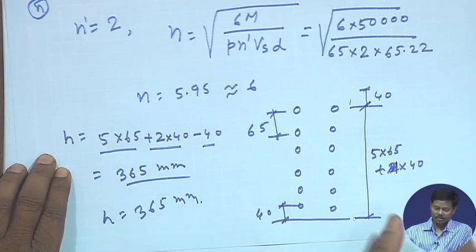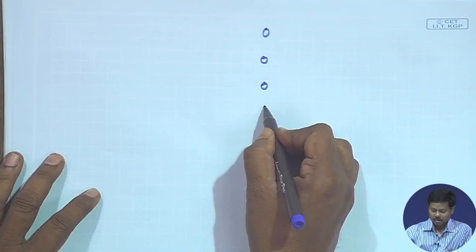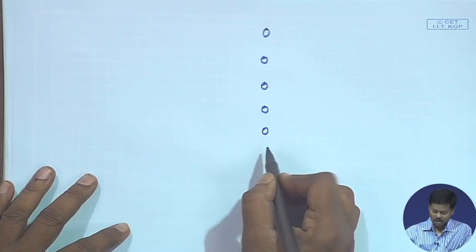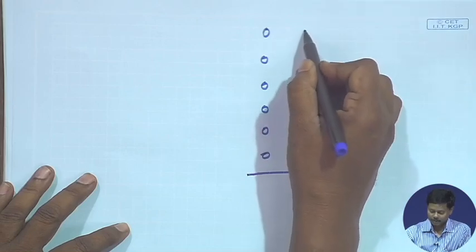Now I have to find out the value of TB, the tensile force carried by the extreme bolt, how much force is going to be carried by that extreme bolt. For calculation of that we have to know yi and summation of yi square. If we put those one by one, then I can find out yi and summation of yi square, that is this 336.